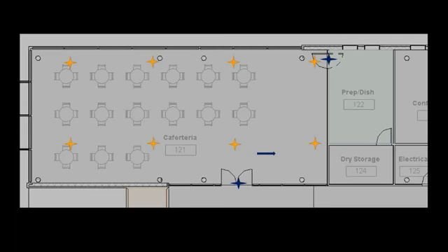Again, this is all about vectors, points, 3D calculus. From there, we'll do the cross product with the z vector and get these two normals from the wall. And then we'll move that point from the center of the room outwards, and now we have points all throughout the model looking like this. So now we do the same thing. Are these spaces in the room? Yes or no? If they're not in the room, then we get rid of them. If they're in the room, we have them. Another thing we're doing is we can count, based on CFM, how many diffusers we'll need.